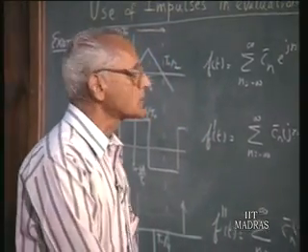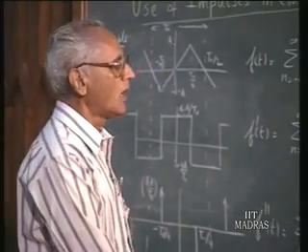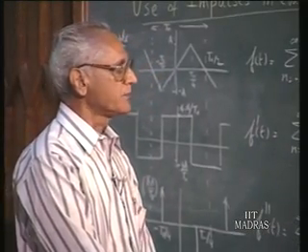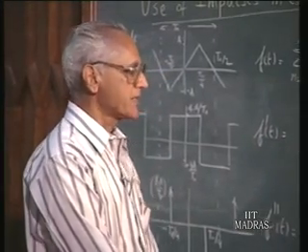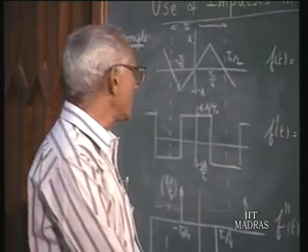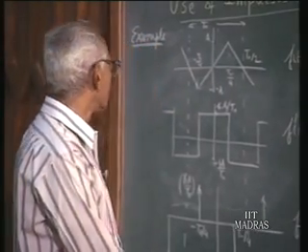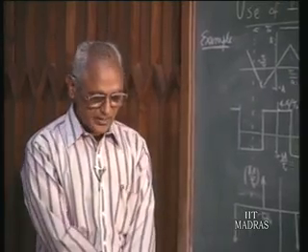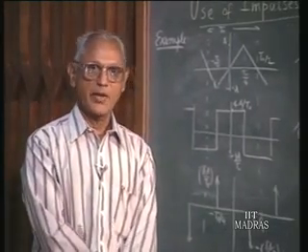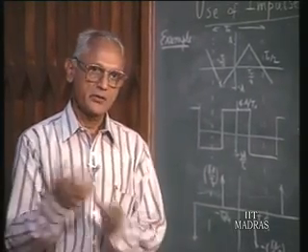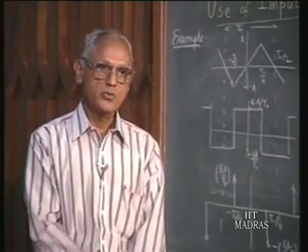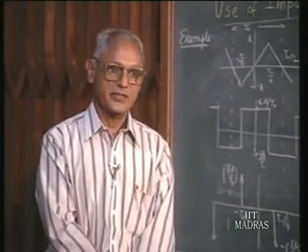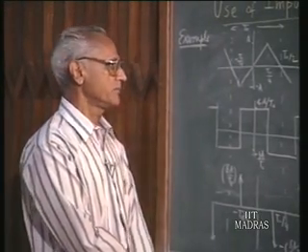And also we saw how the facility provided by impulses in the integration procedures can be availed of in situations where either the first derivative or the second derivative, as in this case, contains entirely impulses. In that case, it would pay us to take the derivative and find out the Fourier series for that, and use that information to find out the Fourier series of the original waveform as done in this case.